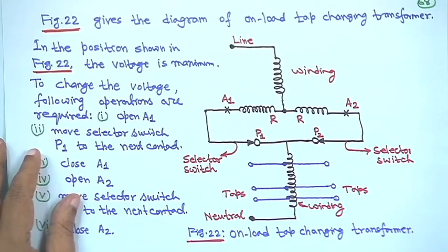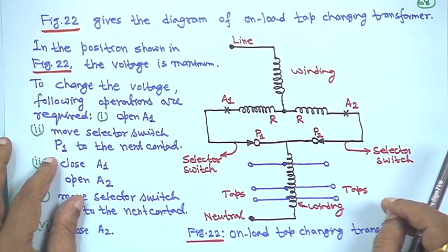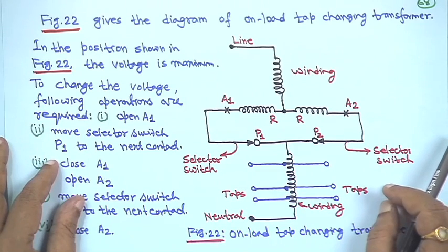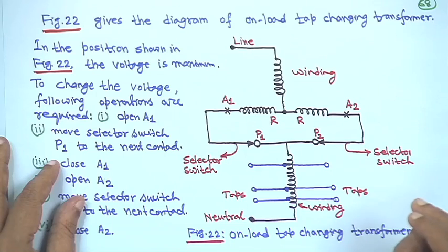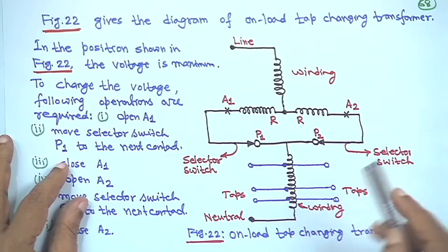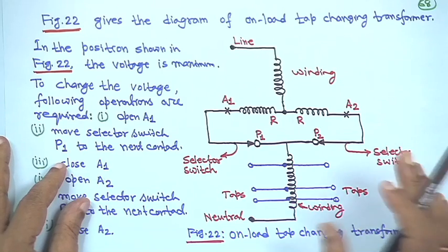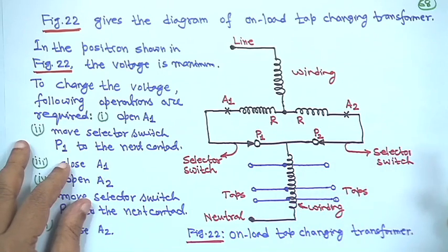Generally in a power transformer, you will find that tap changing may start from 0.625% up to plus or minus 10%, right. So, if it is 0.625 percent on one side, then the total taps on the lower or higher side will be maybe 32, right. I mean voltage can vary from 0.9 to 1.1, but it depends on the design.